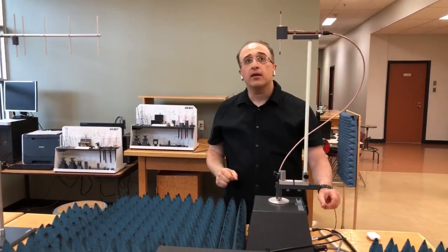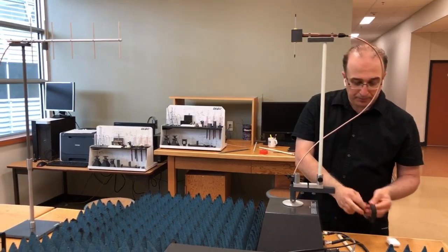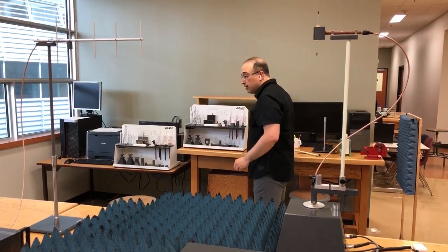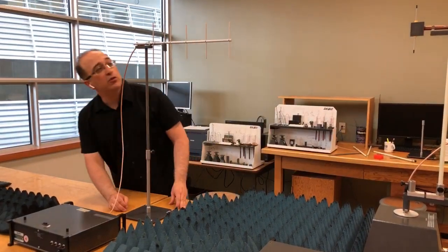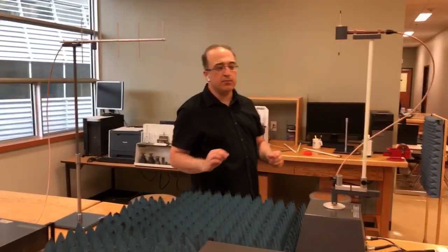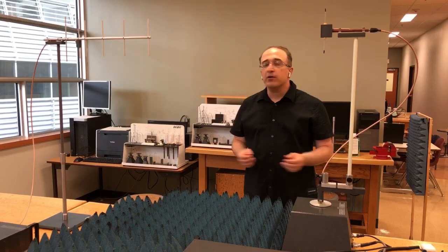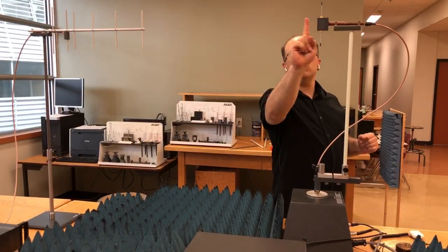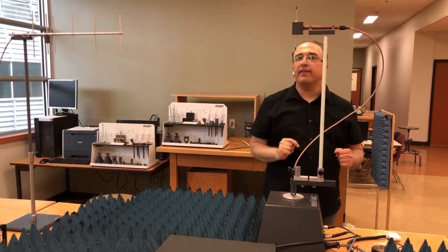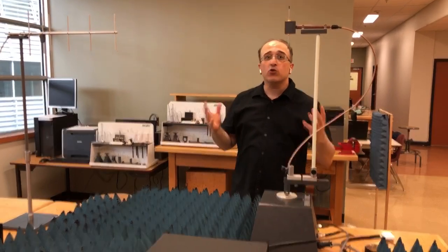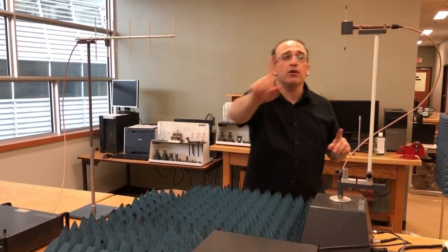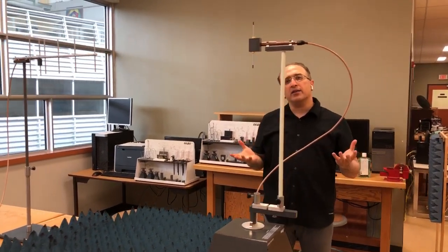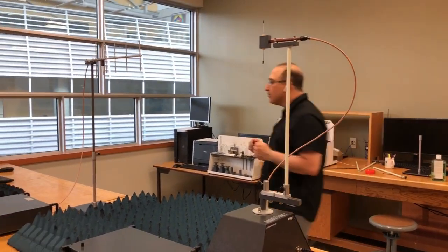And also going to make sure that the Yagi-Uda antenna is properly set up compared to this. It seems to be reasonable. So I can now start collecting, and if you collect like that, this antenna is going to move again azimuthally like that, and that's going to be your H-plane. Note that again, this is co-pol because this is vertically polarized, and this is also going to be vertically polarized. So let's perform our measurement and see what we're going to get.